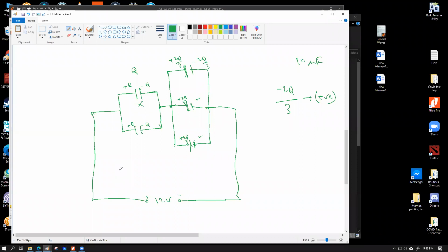It's a basic idea of charge distribution for the disconnected part of the circuit. So now if I go for the same equation set, Q equals CV, C is a constant. So whenever for Q charge, if I assume that the voltage across this plate is V, so Q equals CV. So if Q gives you V, then necessarily 2Q by 3 should give you 2V by 3.